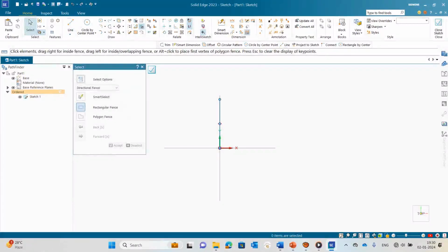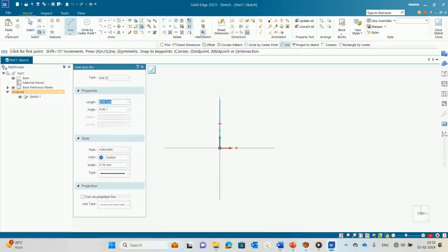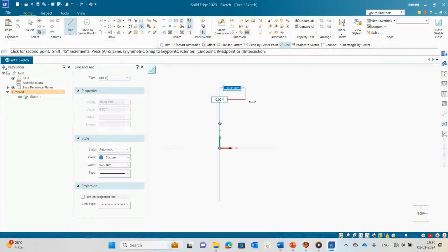From here I am planning to design an atomizer with around 5 mm liquid tube diameter. Since this is a revolve, I need to make the length 2.5 mm, at 0 degree.